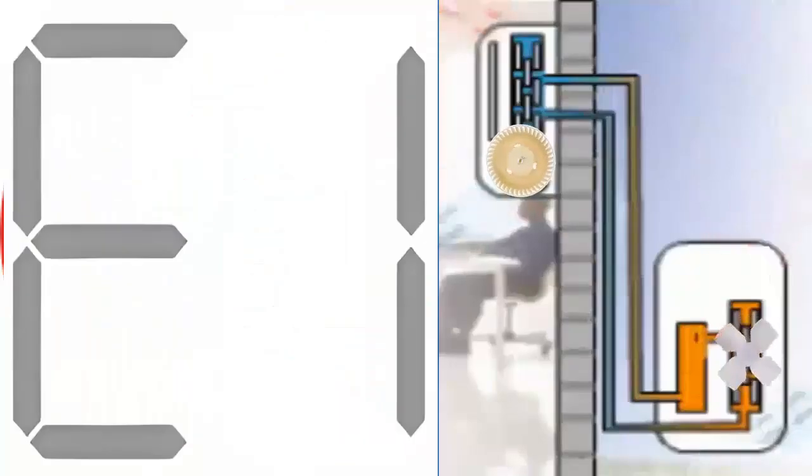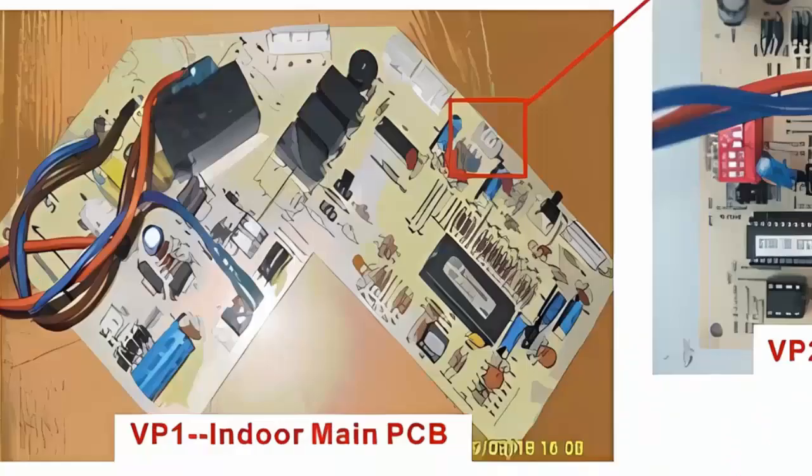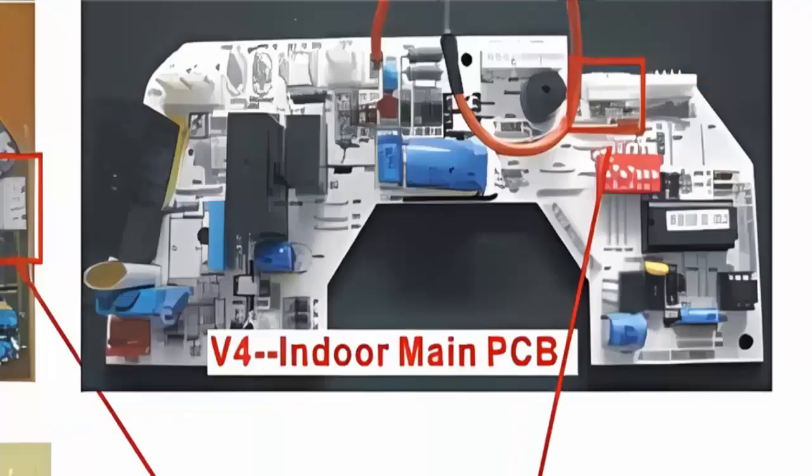7. If the error persists after changing the sensor, it is very likely that the problem is in the electronic board of the indoor unit. In this case, it is advisable to perform a visual inspection of the electronic board, looking for abnormalities.